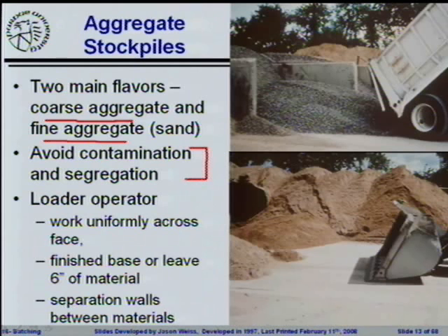Where these materials are stockpiled, they need to avoid contamination and they need to avoid segregation. Every time you handle rocks, every time you handle aggregates, you have the potential to screw it up. Nothing ever goes great when you start off with aggregates. You never make them better by touching them. Every time you touch them, you have the potential to ruin what's going on.